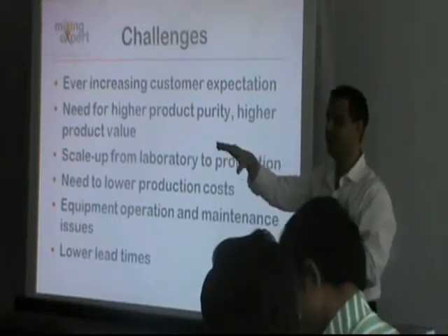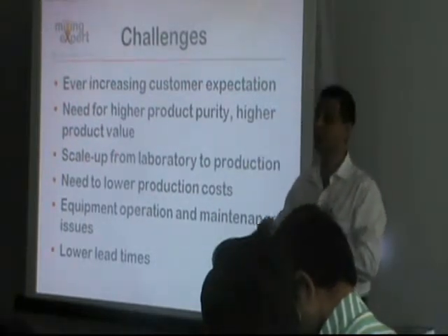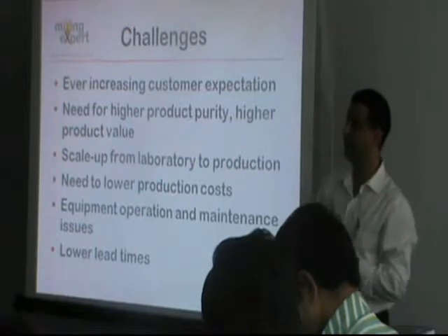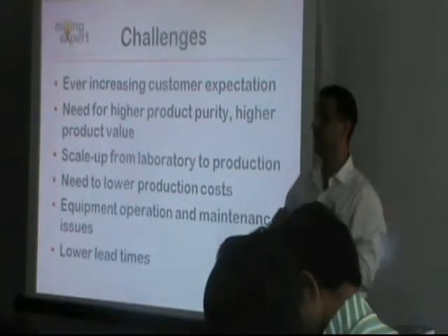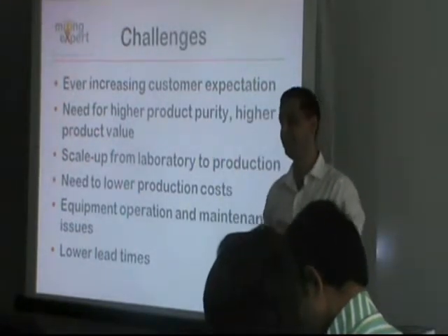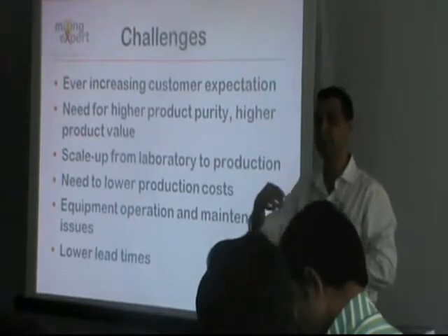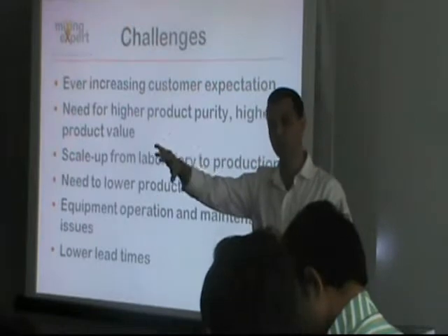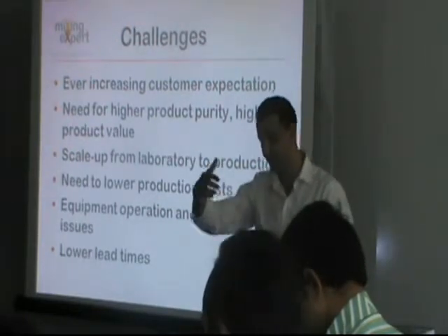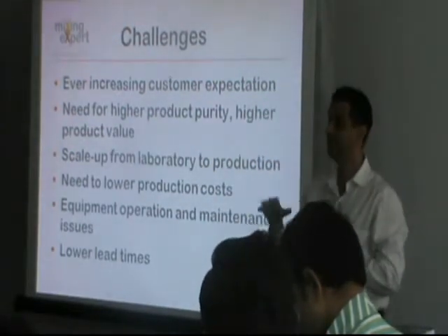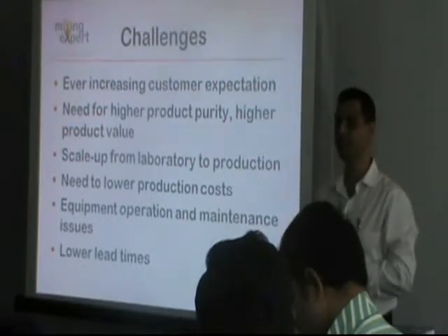So voltage, current and power factor. Motors are designed to operate efficiently at their maximum rated capacity. So if it's a 7.5 horsepower motor or 5 horsepower motor, its efficiency will be the highest closer to the rated capacity. At a lower capacity, the efficiency is lower, so the power factor will be low.